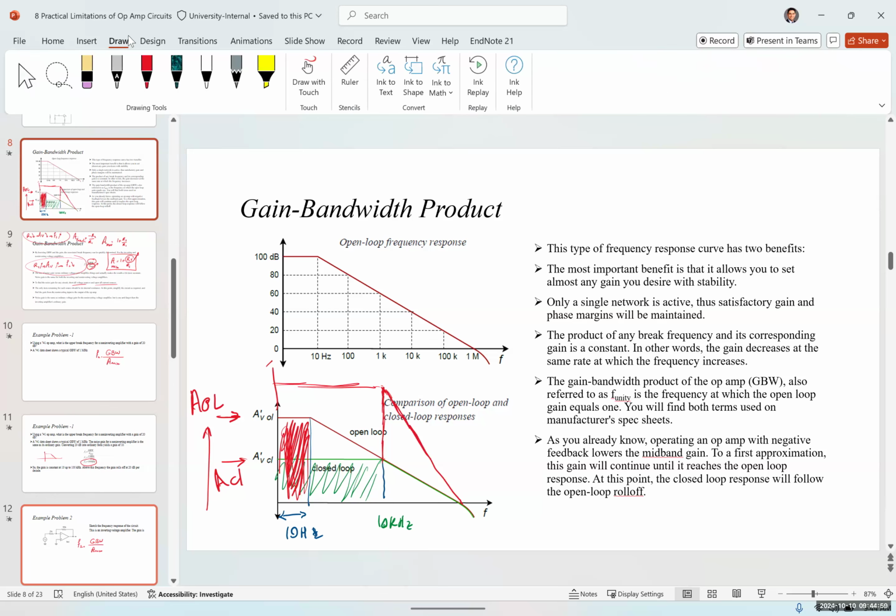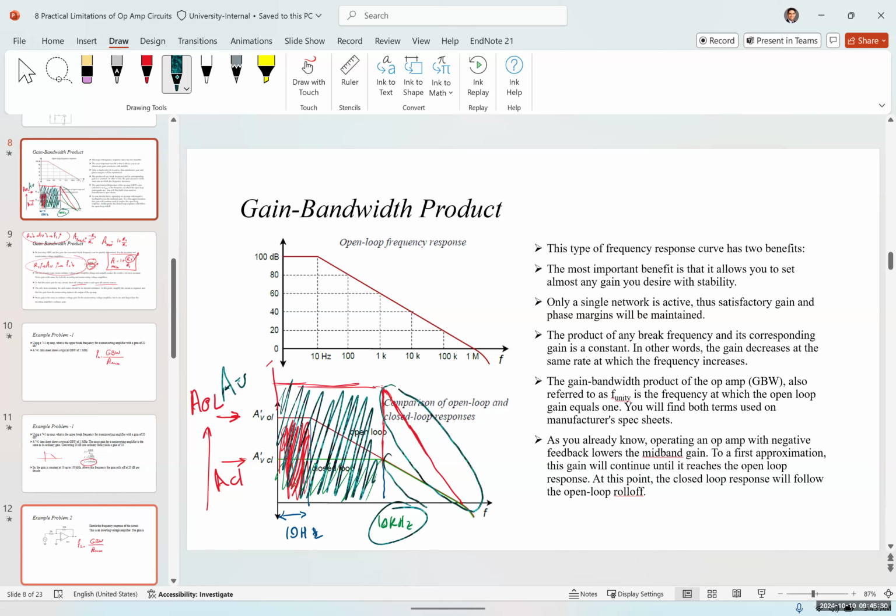So now it's going to look like this, and I'm going to draw it with this bluish color. Now the frequency would be like this. The gain is significantly higher, but the frequency is still around the frequency of one of those stages. So this is one difference. You multiply the gains, you have the cascading effect, but the frequency response remains the one at upper frequency.